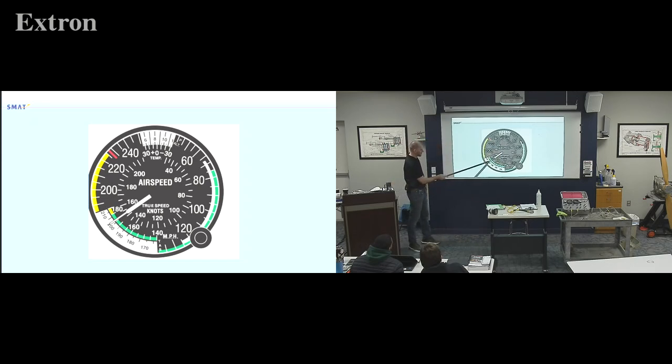I took 203 and I did 203 divided by? No, times. Divided by 1.15. I had to do it both ways to make sure I had the right number. And that gave me the 176. He was one ahead of me. He's like, hey, I got a scale. We might even call this a whiz wheel of sorts. He just went up to 203 and then transferred it over to where that is on his automatic conversion scale.